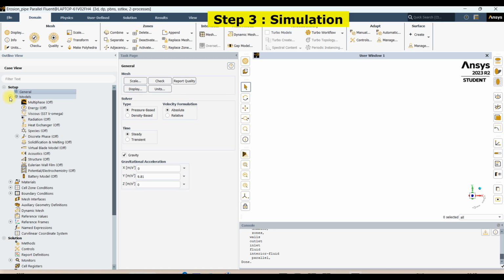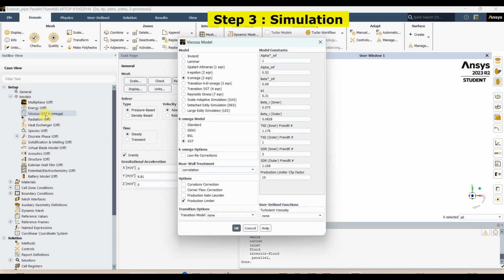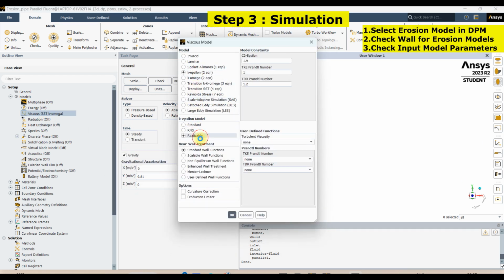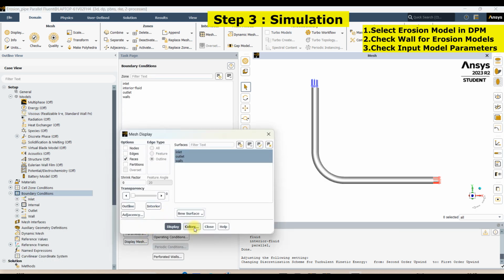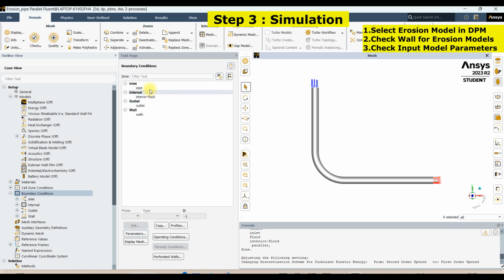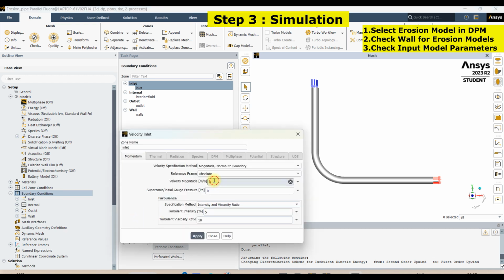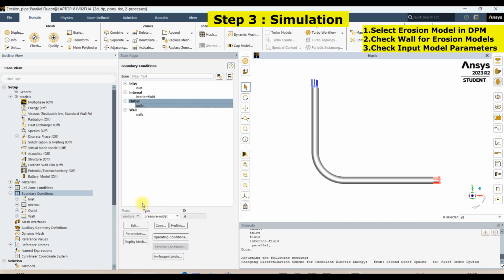For the viscous model we can use the k-epsilon realizable model. And here we see how the model looks. Here we can define the mass flow rate. Here we can define the velocity as 0.25, or 0.5 meter per second. Outlet you can declare as a pressure outlet,